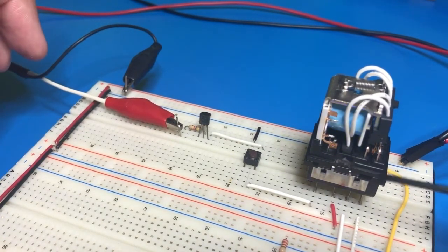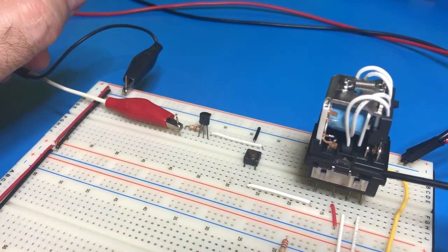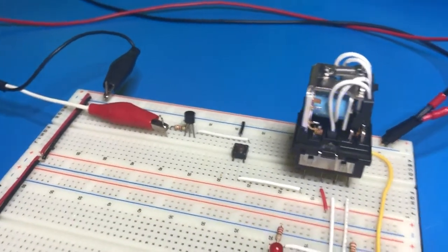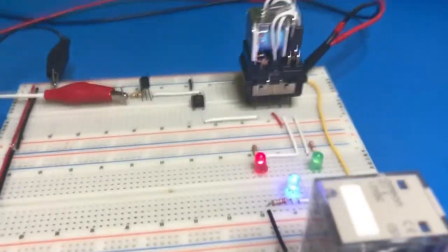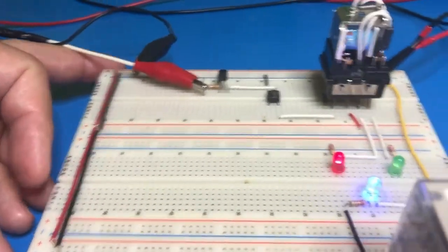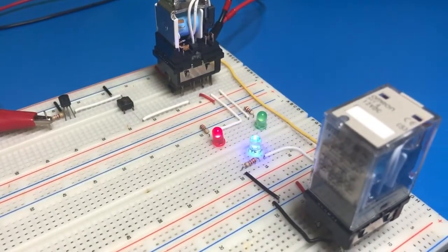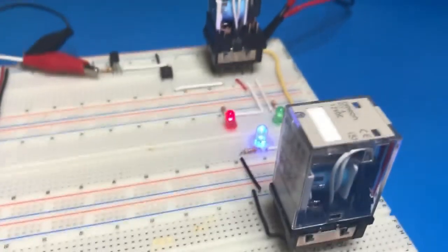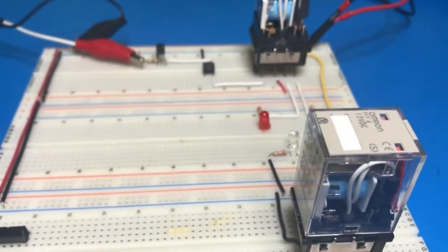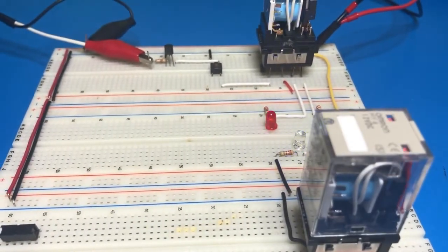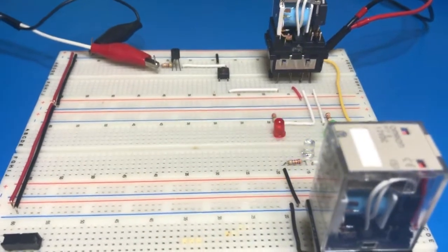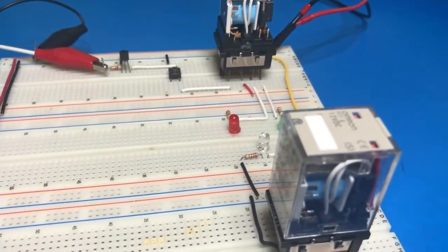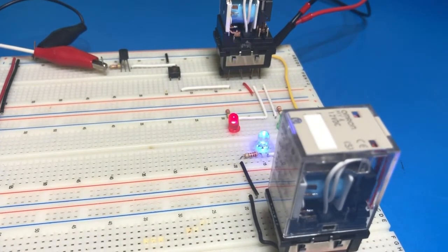So if it's a switch, can we control a relay with a relay? Yes, of course. So look what I have here. I have a second relay that is controlling the blue light in here. This one still has the cover, but you can see how the relay moves, and it's being controlled by the contacts of the other relay. And these are the building blocks of a relay computer.